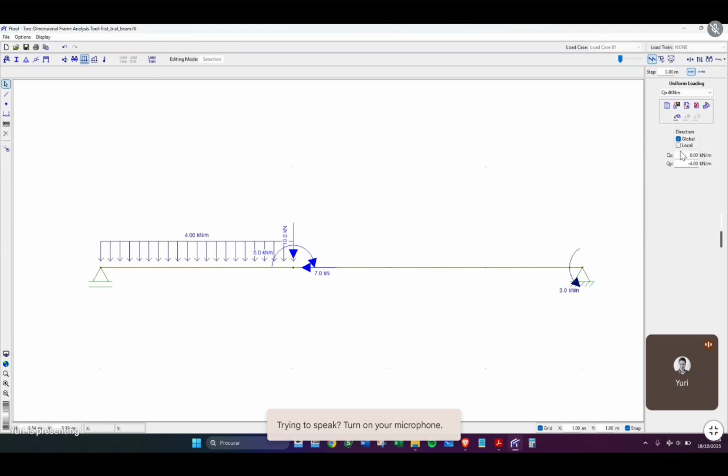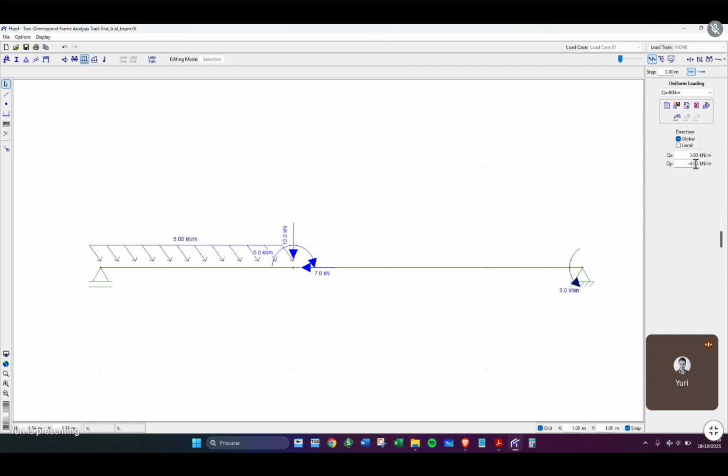And also, if you apply in the X direction, you will create a distributed load from the top to the bottom of the frame, let's say like 3. You can change that. This is quite interesting. Put 0 here, as you can see. Okay, so you can play around with this, like 5, and you can see that the load is going to be tilted with the resultant force here. All right. In this situation, we were just talking about 4 and 0 here.